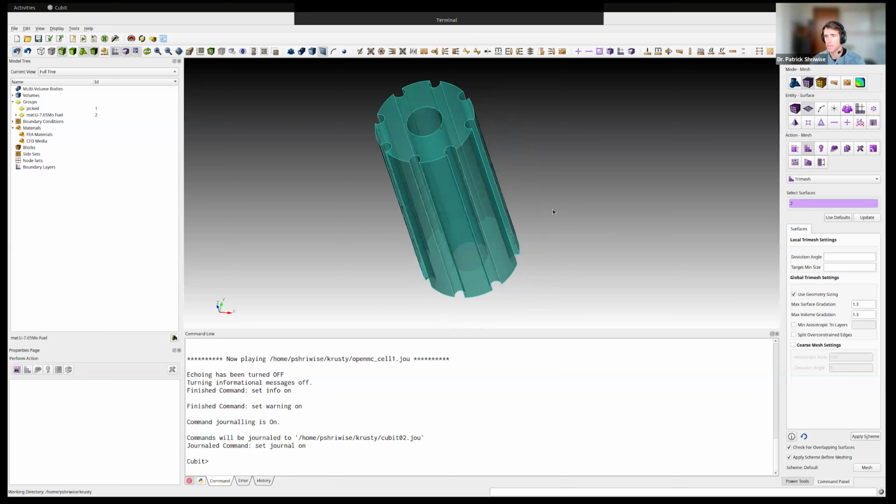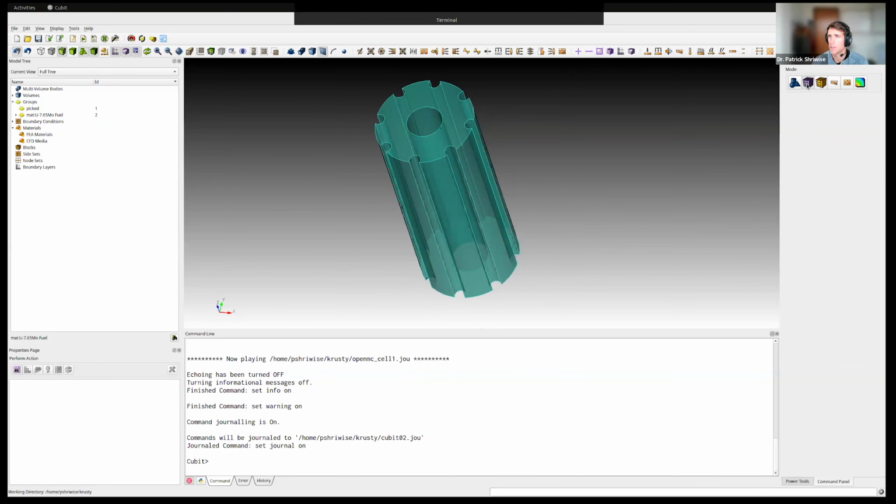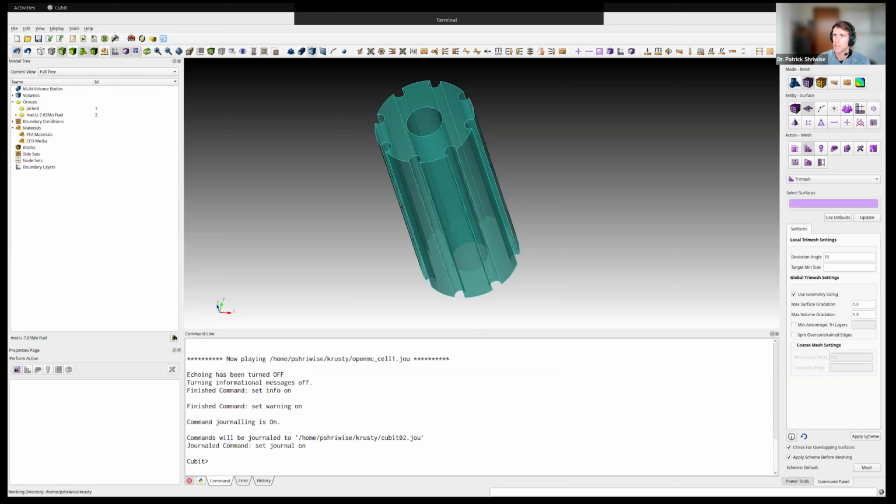But now we can take that a step further, and take our originating neutronics model and start to build up a multiphysics coupling mesh. The first thing that we're going to do is build a DAGMC surface mesh. We'll be doing this with the Cubit tri-mesher. So in the GUI here, I've selected mesh. We'll just start over and do that. We'll go to mesh, we've selected surface mesh, and we'll be using the tri-mesher in particular.